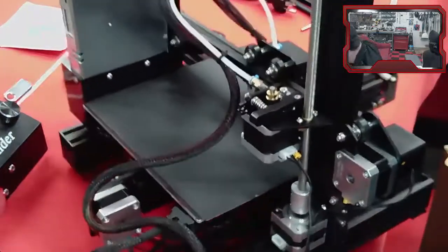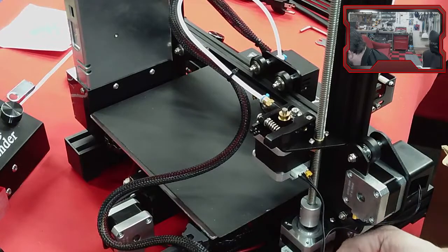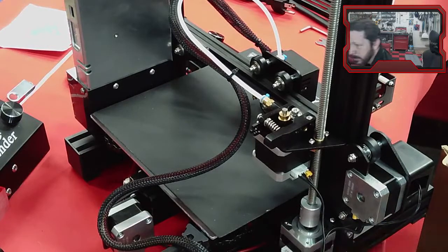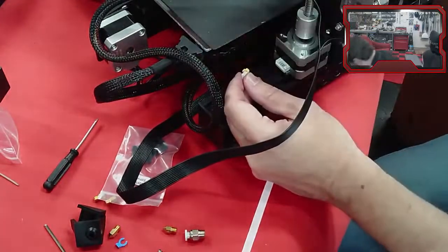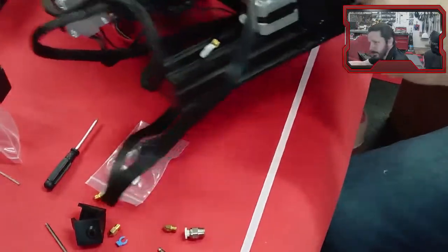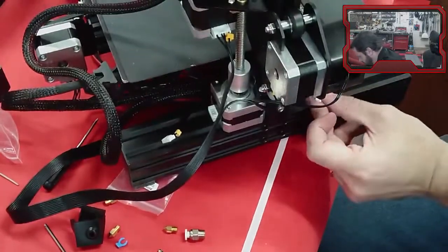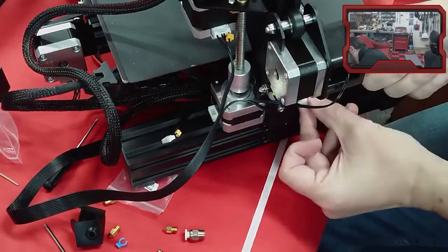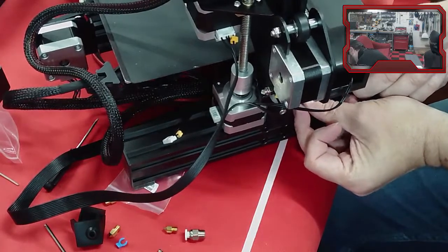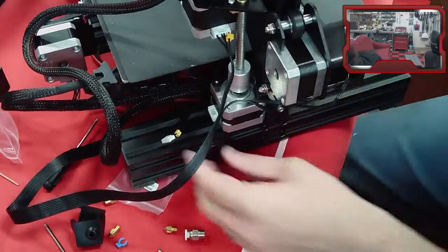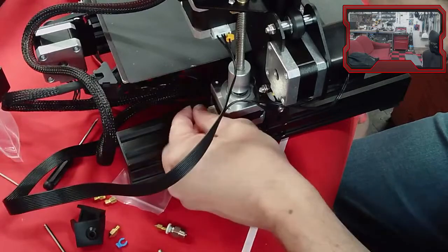All right, and got one left here. This one should have a Z on it. Yes, a Z, and it's going to plug in here. I do need the Z endstop. I don't see that. Oh, it's right here. So the Z endstop will plug in right on the Z. The Z endstop is the one that we had to bolt on. All the others were already on there. And then the Z motor. Again, the Z endstop is the one I said we would probably have to adjust.